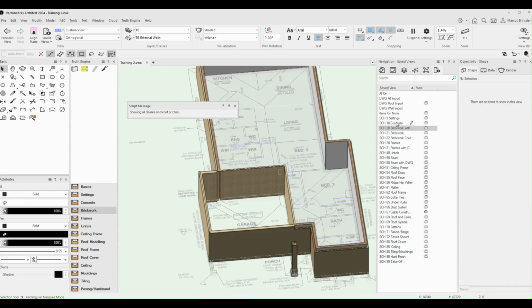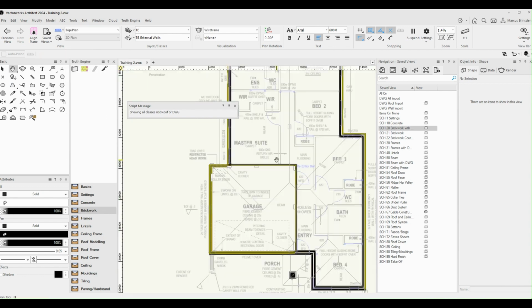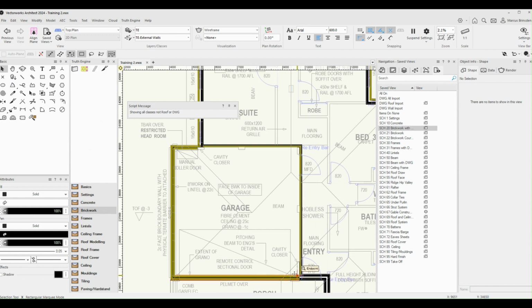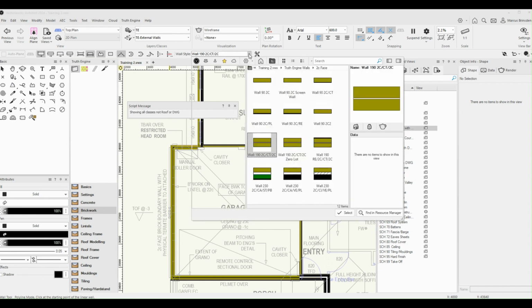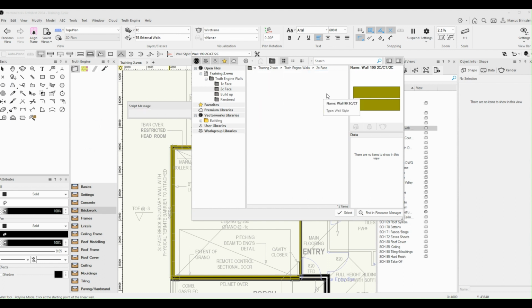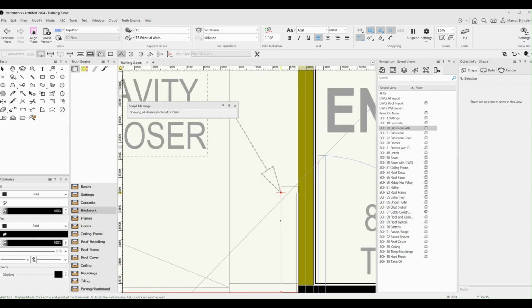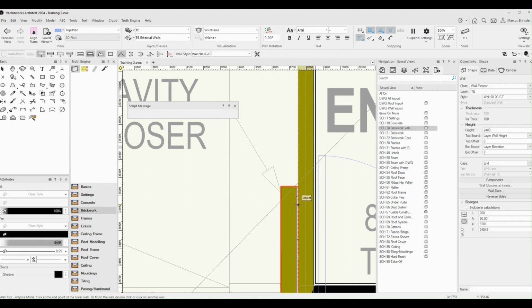Okay, so while we're working on that garage area, we shall do our piers. We'll go to our top plane view. You can see we have these attached piers, so we have a wall type to handle that. So you should use two course cavity ties, so that will give you your wall ties, wire ties that you need, as you can see there with that black, thin component there. And when we draw these walls, basically clicking on the outside, and there's our wall in the right location.